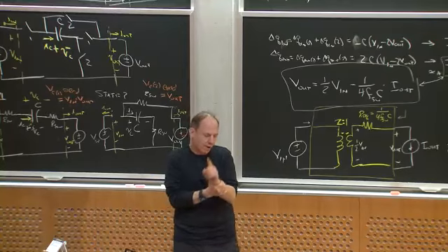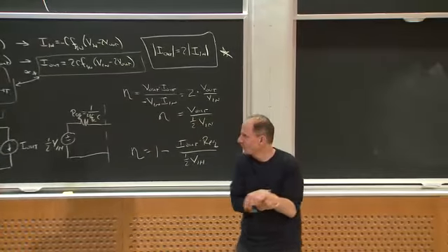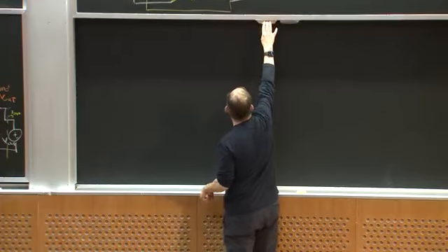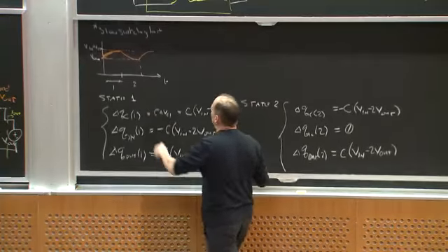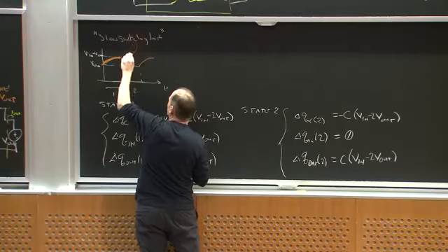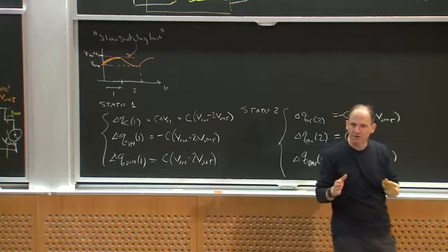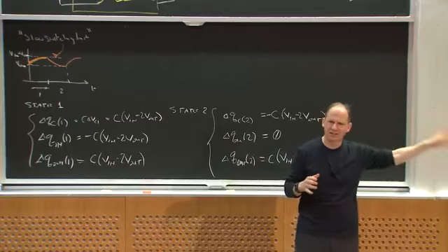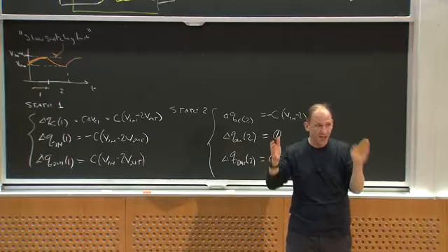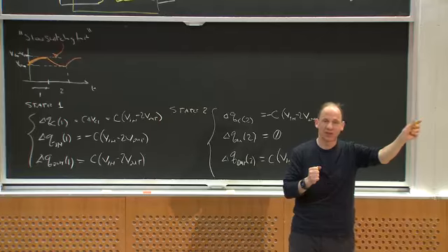Okay. Now, there's an exception to what I said, or a limit to what I said. This operation is all in what I've been calling the slow switching limit, right? This limit right here, where I'm fully charging and fully discharging. Suppose I want to get higher efficiency, and I'm forgetting about gate losses and capacitor discharge losses and stuff inside the switches. I'm just talking about the charge transfer losses. I can switch faster and faster and faster. That output resistance keeps drooping, right? Keeps getting smaller, and that's better.